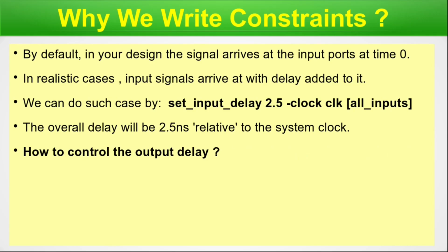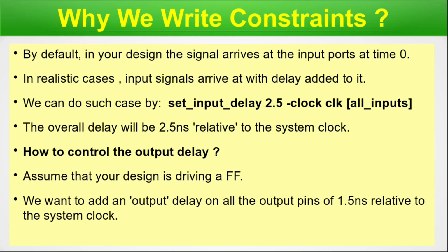How to control the output delay? Well, we can do that. Let's see how. Assume that your design is driving a flip-flop. We want to add an output delay on the output pins of 1.5 nanoseconds relative to the system clock. So how do we do it?